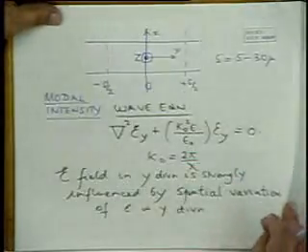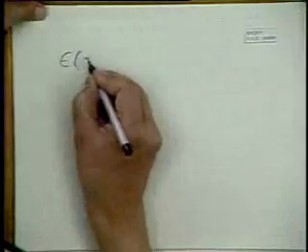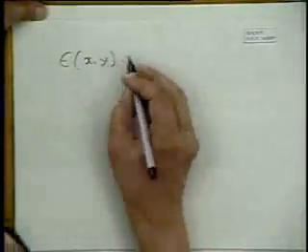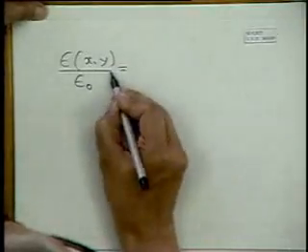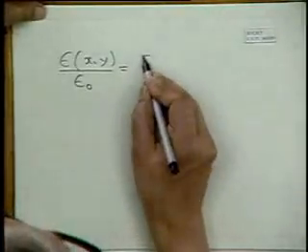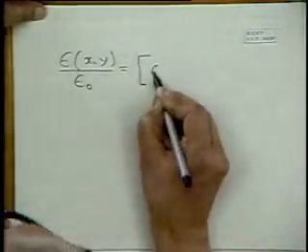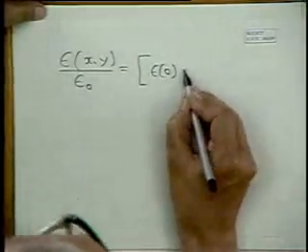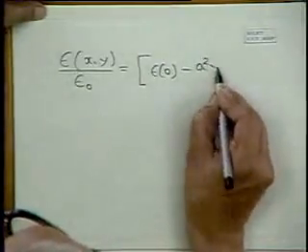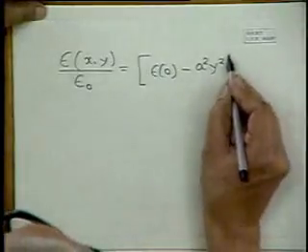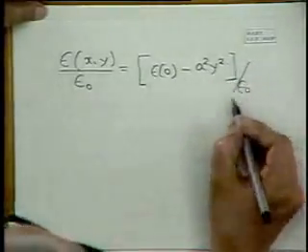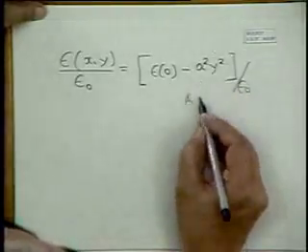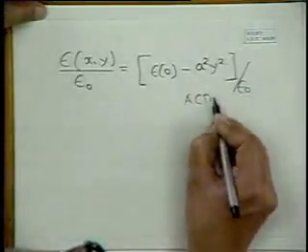So you have a dielectric constant, a function of x and y, that's the relative dielectric constant. We can say that it may have a parabolic variation of this type, with a squared y squared within the active layer.